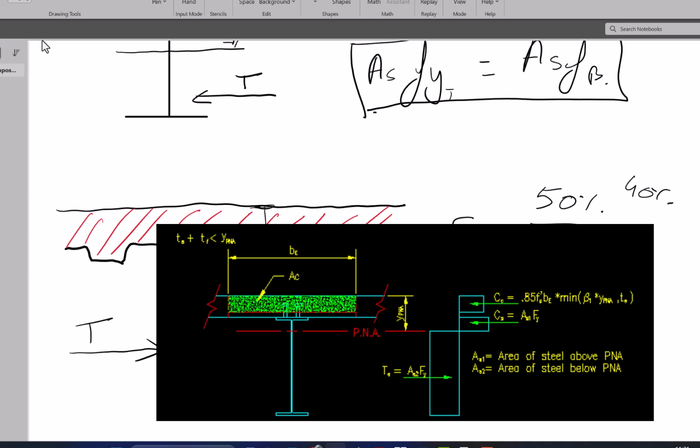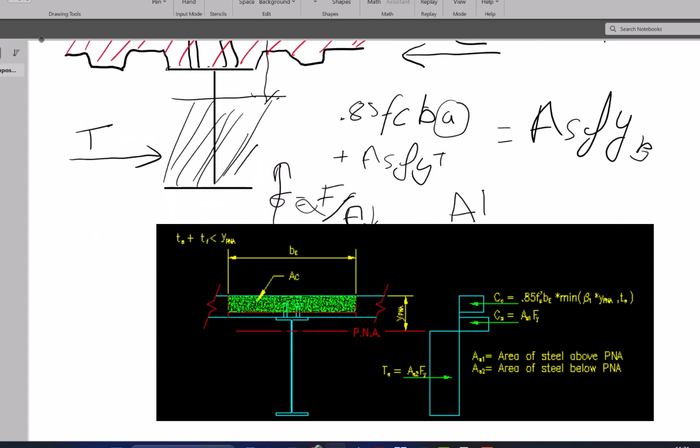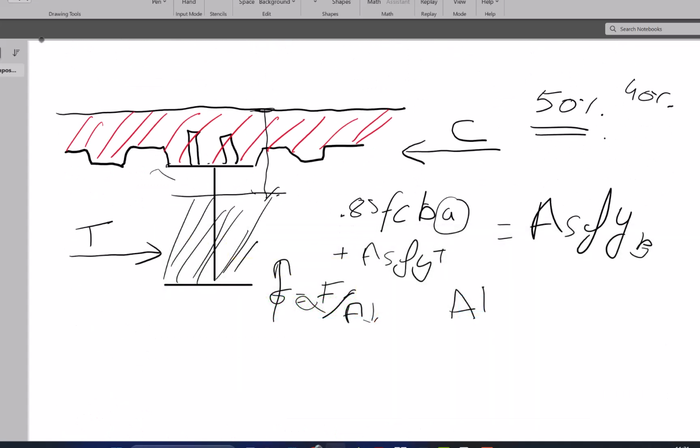So if you have a higher value of area contributing to the stress, you will have higher allowable stresses. That's how composite beams become more economical, because this particular section in concrete is taking part as a compression element.